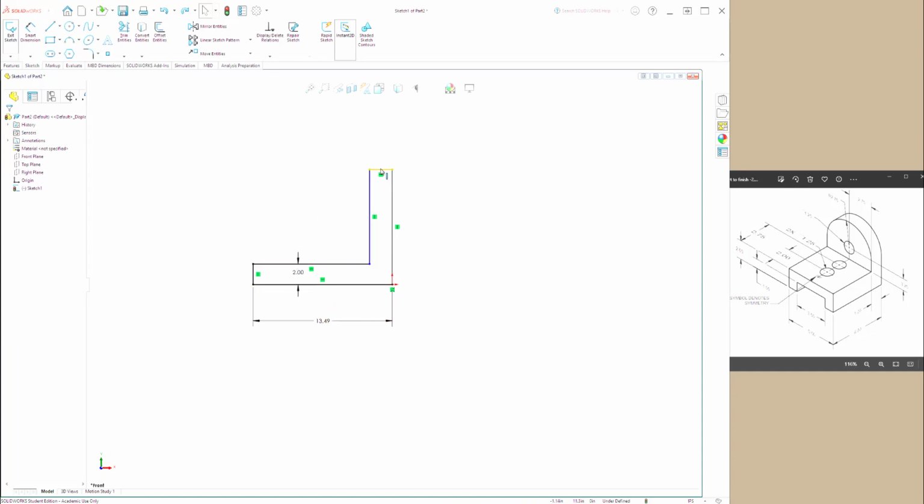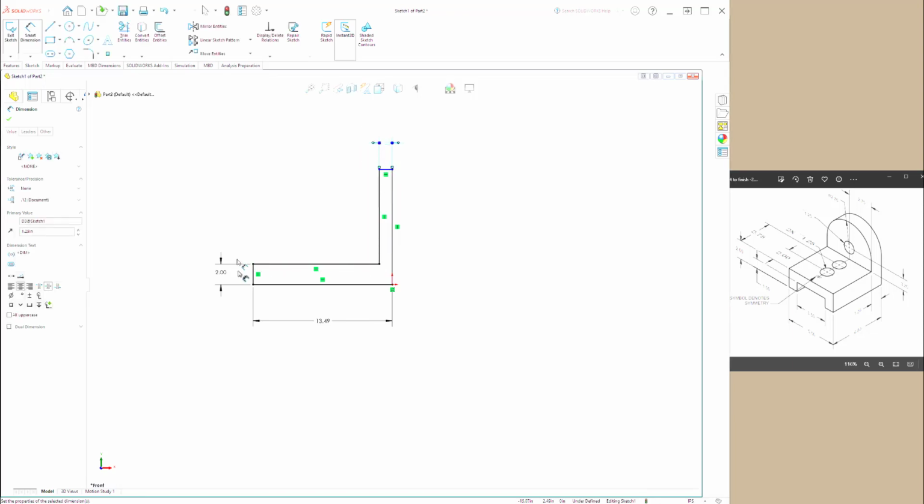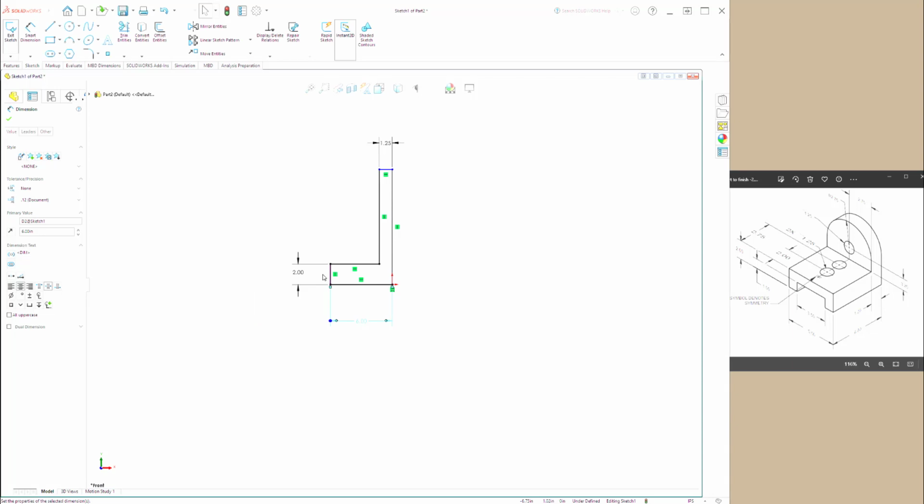What we do need to keep in structure is what the width of the back happens to be. And that says that it's 1.25 here. So we're going to go ahead and add in this smart dimension here and make this 1.25. And what that does is that holds the shape of the part. Now, if we were to choose the OK button or the green check mark and come back and change the 6-inch dimension, notice that the shape now keeps the part design.